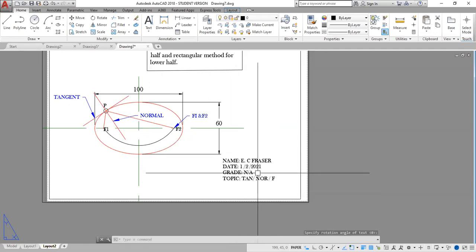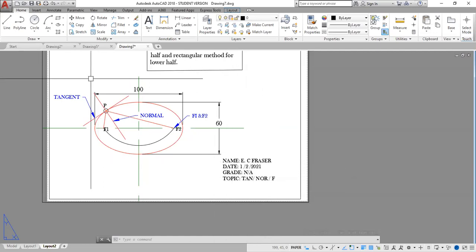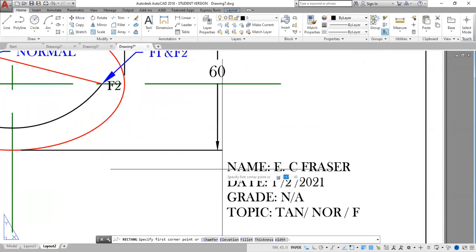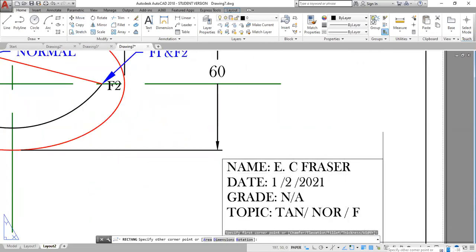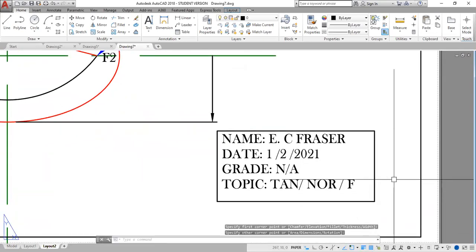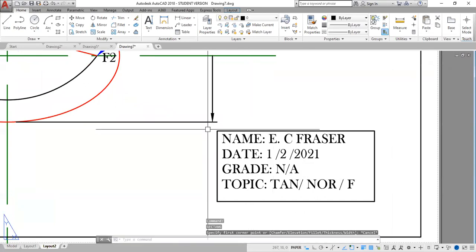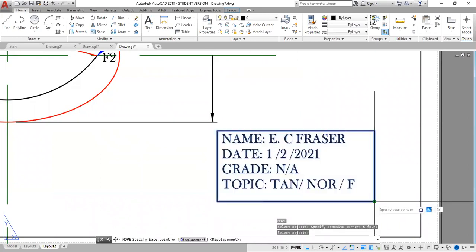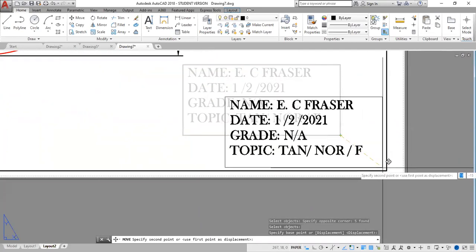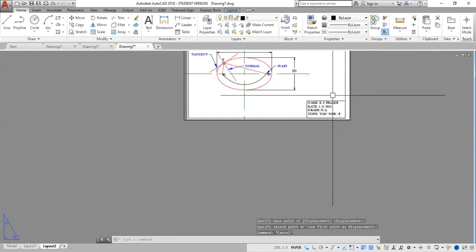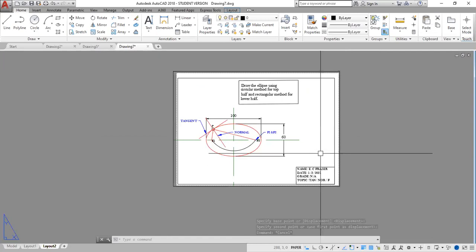All right, so what that does, this creates a little title block here. I could use a rectangle here. So I'm creating a box around this. Escape. Now I could move this, M, enter. Select here, enter. Grip this here. And I could move everything down to this point here. Escape. So right then and there, I create a quick title block, right?